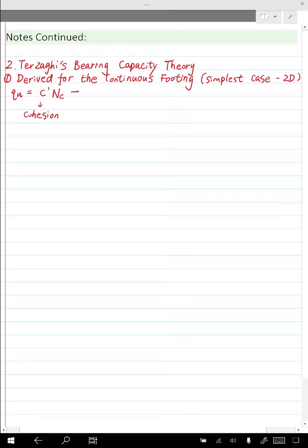Are there any other ways that we can use to improve the bearing capacity of the object? What if I place some sandbags on the sand surface? Will that help stabilize the object or enhance the bearing capacity? Intuitively, it seems that's possible, right? Actually, that's also the truth.